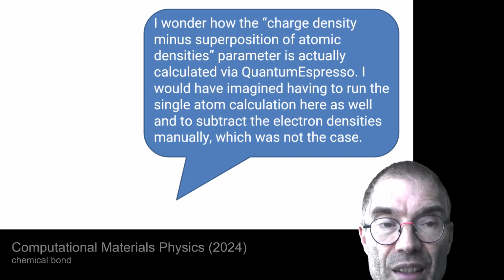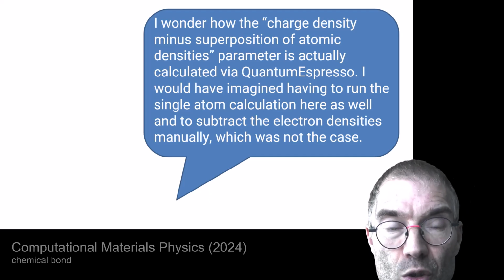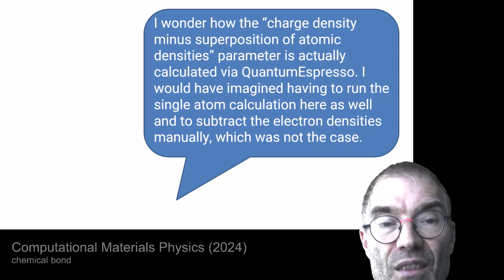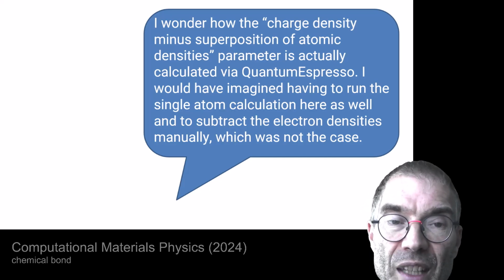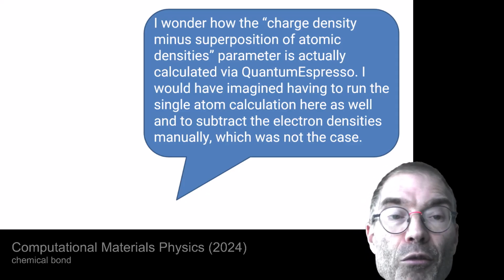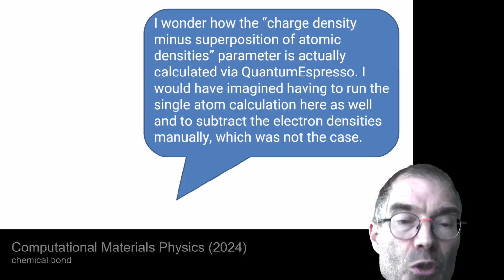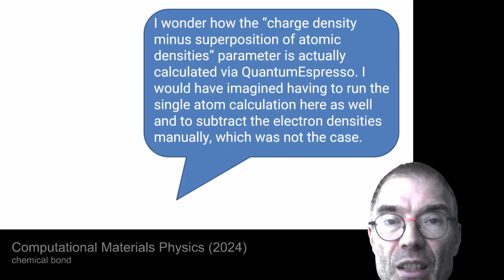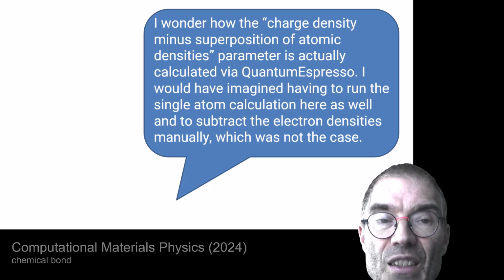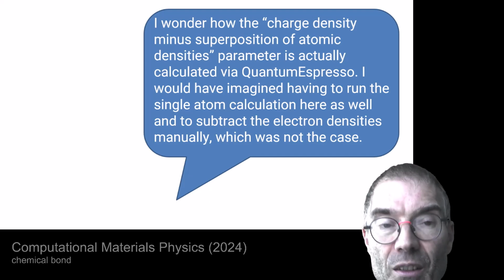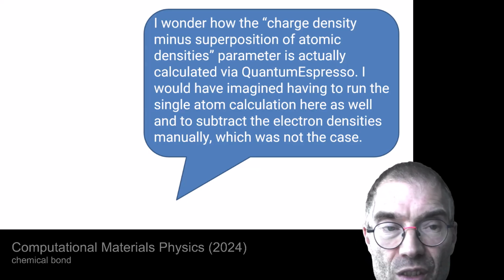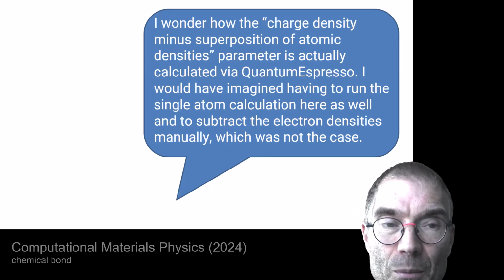The answer is that when you use these post-processing routines of Quantum Espresso to display the charge density, then it will calculate internally the charge density of free atoms, but not with a supercell, not with such artificial FCC lattices, but with a module that really can treat free atoms for real. So there is no periodic boundary condition, just a free atom calculation directly for the free atom.